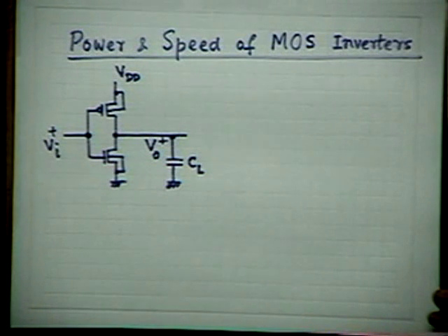So you see that when you consider a CMOS inverter, I have already told you a number of times that the load it sees is a purely capacitive load because the input is a MOS capacitance. MOS capacitance is practically a lossless capacitor, almost an ideal capacitor. So the load is a pure capacitance.